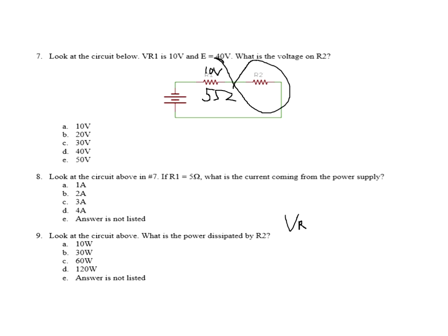Well, the volts on R2 is equal to what? What do we find for R2? 30 volts. The current in R2 is what? Well, series circuit, it's all the same current. And we said how many amps was that? Okay, it was 10 volts over there, divided by 5 ohms, so that was 2 amps. Okay, so 30 volts times 2 amps would give me 60 watts for that one.